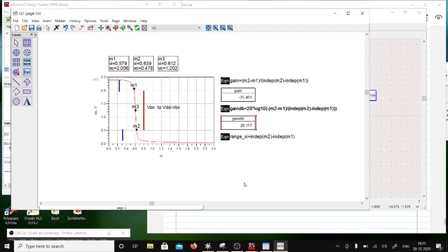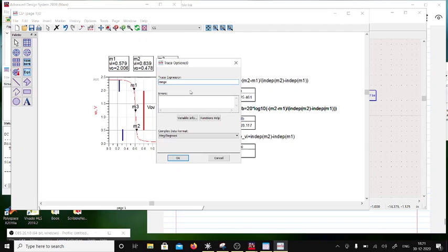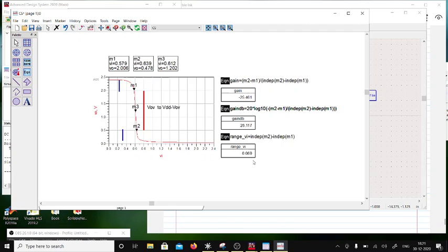Control C, Control V. Range Vi, sorry. So range Vi is only 60 millivolts. So your bias point is around M3, which is 0.612. So you can go 30 millivolts on the left and 30 millivolts on the right. So your input voltage range has shrunk because the gain has gone up.